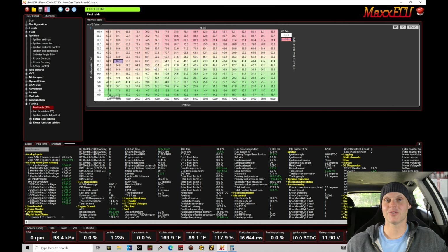Welcome back to our live training session. In this tutorial, we're going to be taking a look at how to dial in our VTEC high cam operation. So this is going to be looking at fuel, spark timing, variable cam control, and even working with our knock threshold table within our knock control routine. So we have a lot of things to unpack and discuss here.